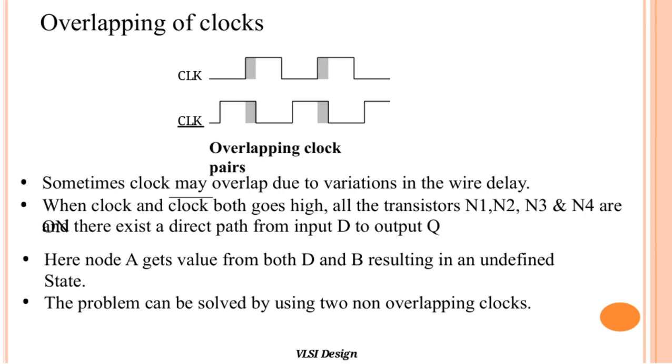To prevent this situation, designers use two non-overlapping clocks, ensuring that the clocks never go high at the same time. This simple but crucial measure helps maintain proper timing and reliable operation of the circuit.